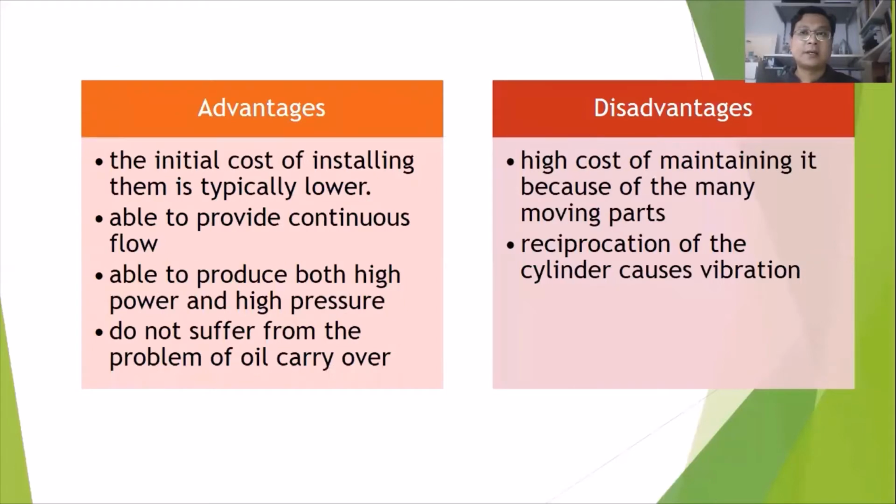So the advantages of this compressor: the initial cost of installing them is typically lower, able to provide continuous flow, able to produce both high power and high pressure, and do not suffer from the problem of oil carryover. And then on the other side, there are also disadvantages. The first one is high cost of maintaining because of the many moving parts.